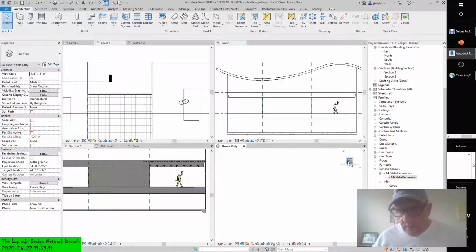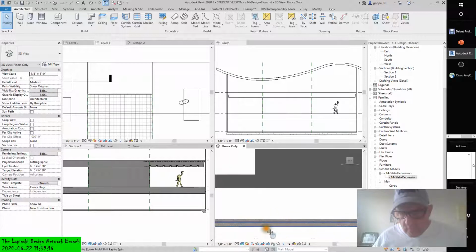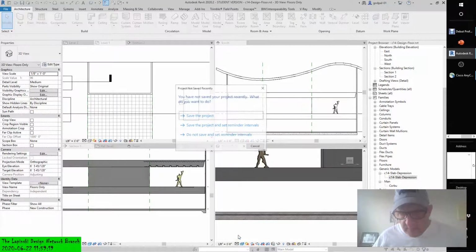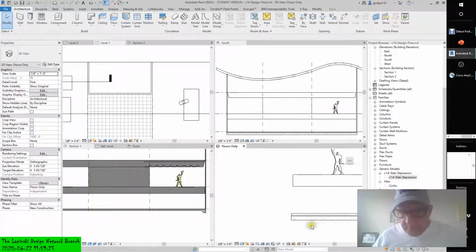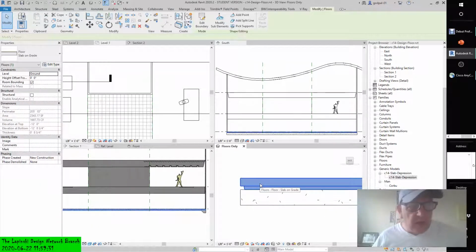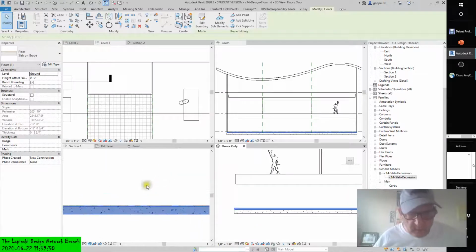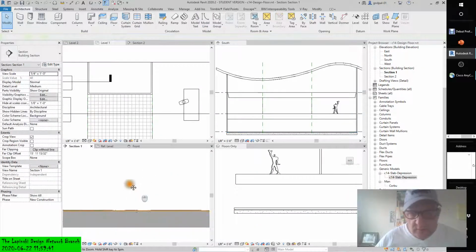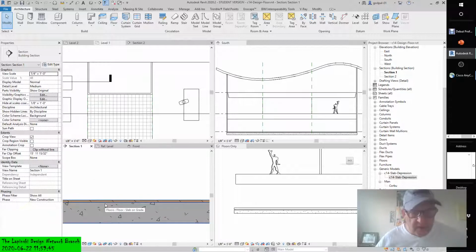And as you can see, on the first floor, if we go to Fine, and we turn off the shading, let's go to Hidden Line. Slab edge. Well, if you look at this, hold on. So all that glitters is not gold. There it is. Looking at it the wrong view. Floors only. All right. So as you can see, there's the extra layer on the first floor.